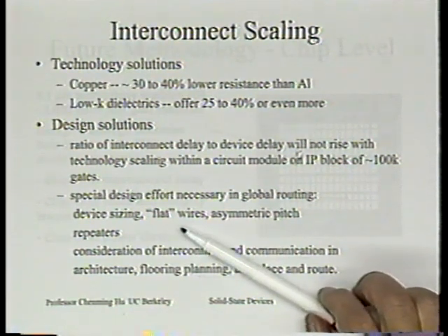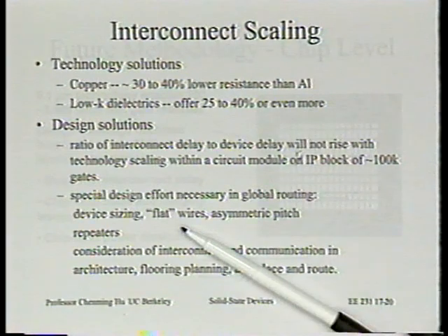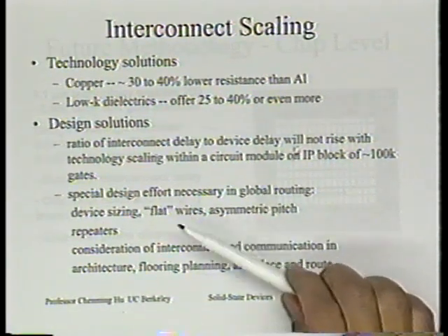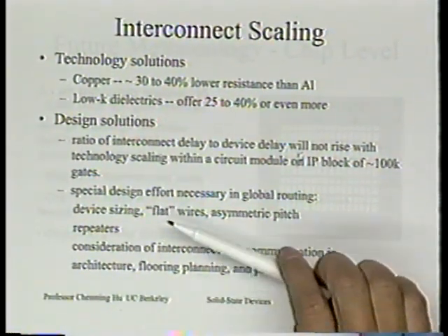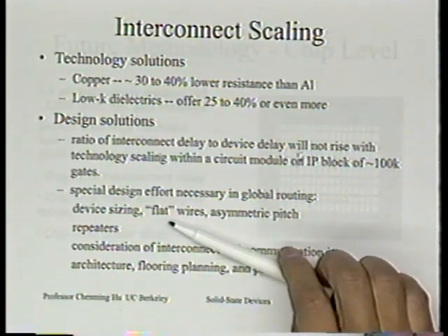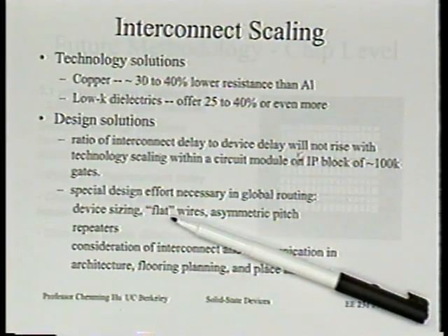Using perhaps, we're not going into detail, but just because the density is not so large, you can play games with wider wires and either taller or flatter wire. Turns out also have other benefits. A tall wire will give us low resistance, but I can also use a wide wire to get low resistance, right?